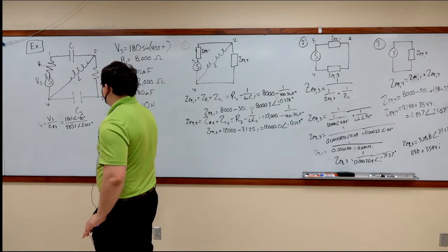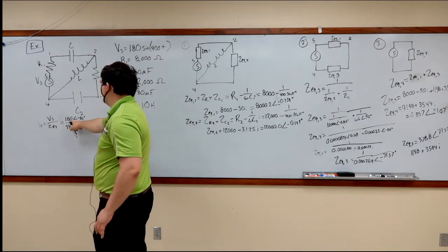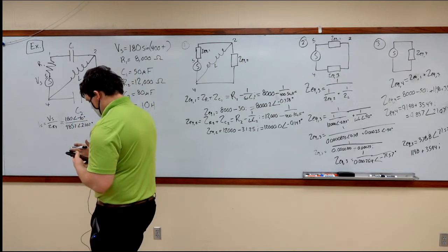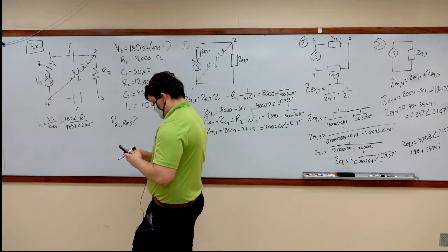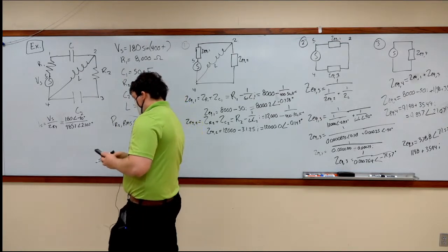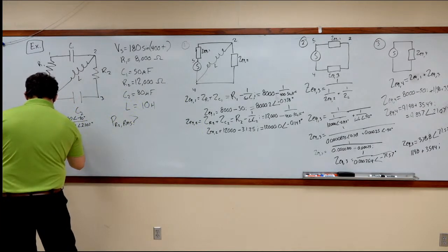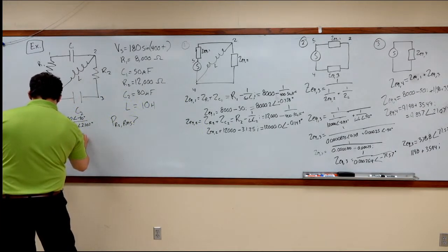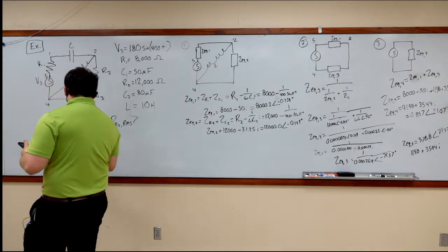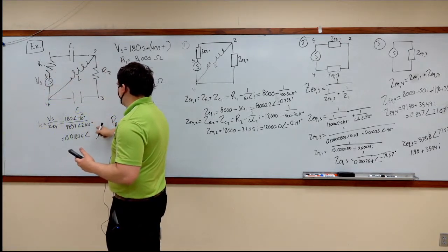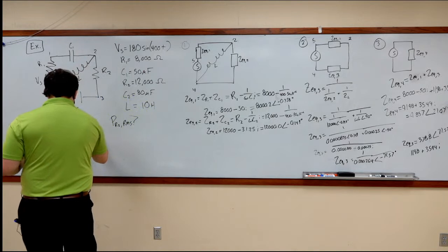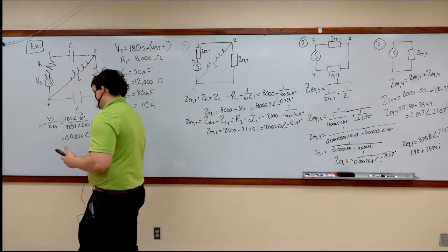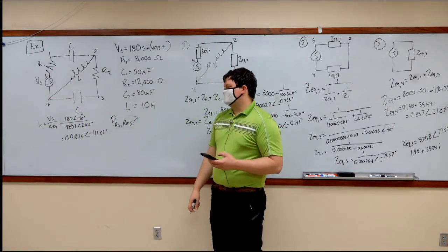Okay. So our IS value, we're going to calculate those two divided by each other. And this is equal to 0.01826. An angle of, here it is, negative 90 minus 21.07. So that's at an angle of negative 111.07 degrees. Well, that's gross.